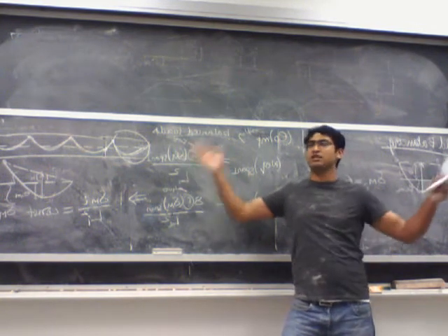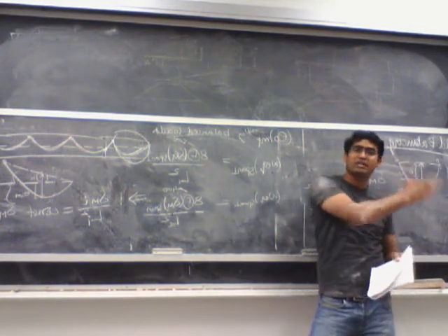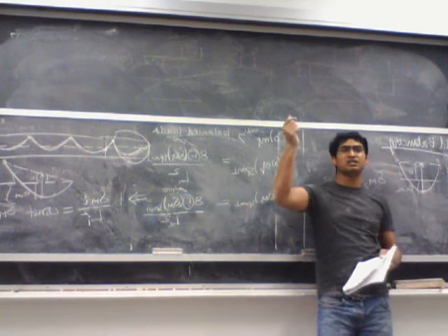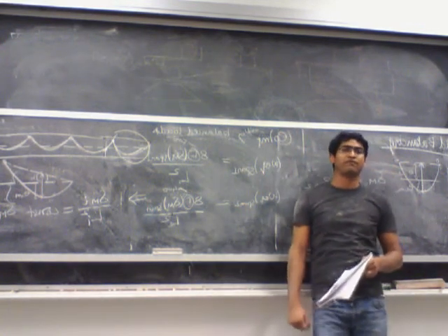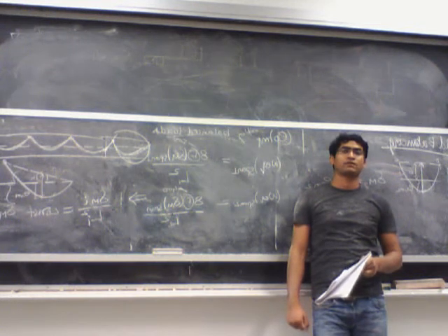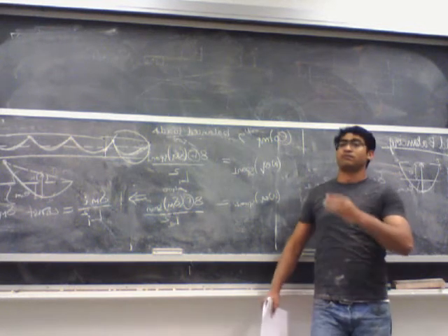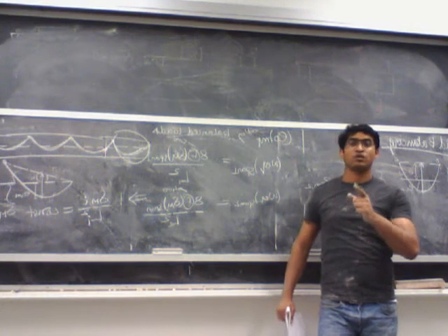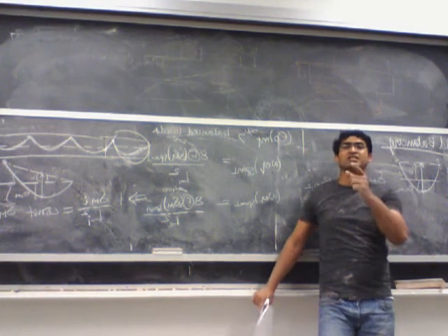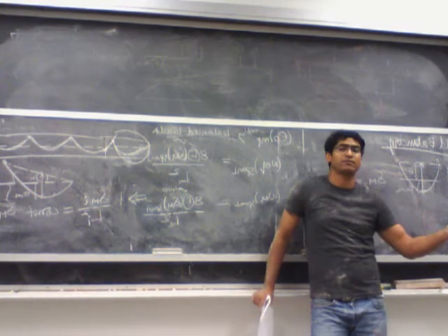So if you have 10 spans, you have 10 values of F, one from each span. You pick the largest F out of those 10, and that actually becomes your final F. Your largest or your minimum? You pick the largest because the largest will satisfy each and every span.